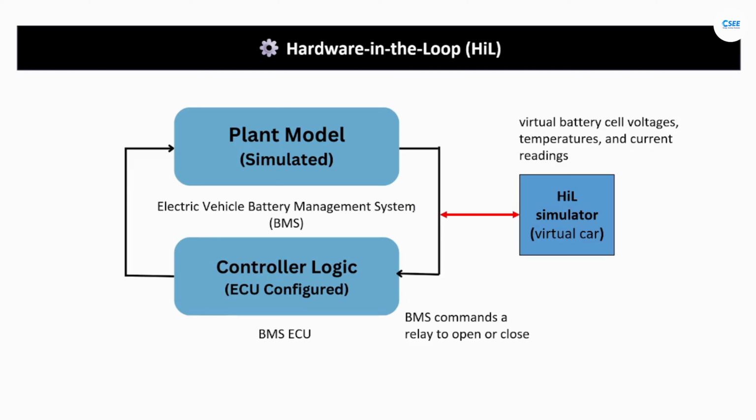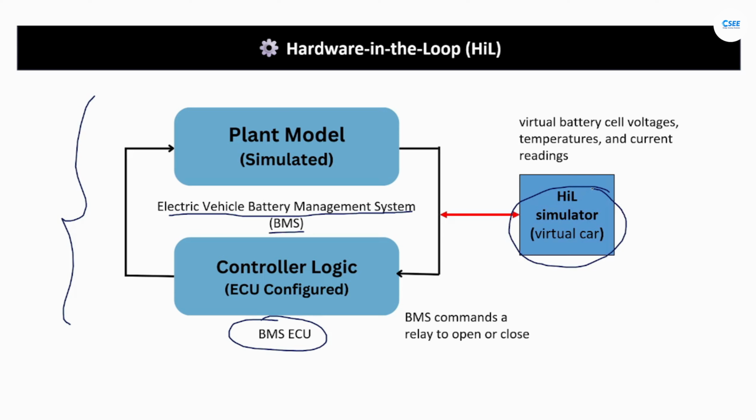Let's take an example. Imagine we are developing an electric vehicle battery management system, BMS. In a HiL setup, the real BMS ECU is placed on the bench. The HiL simulator provides virtual battery cell voltages, temperatures, and current readings. When the BMS commands a relay to open or close, the HiL system reacts instantly by simulating the battery's electrical behavior. Engineers can simulate thousands of driving cycles, faults, and environmental conditions, all without touching a real car.